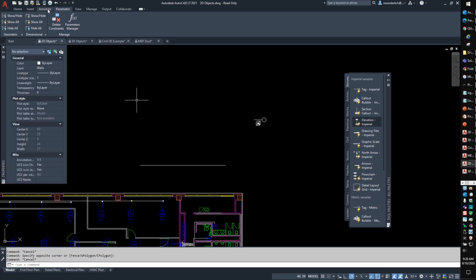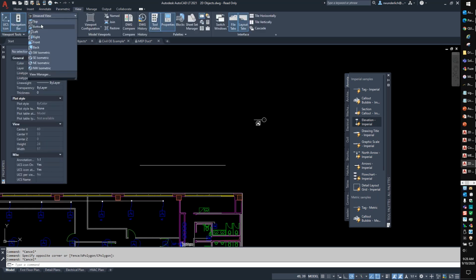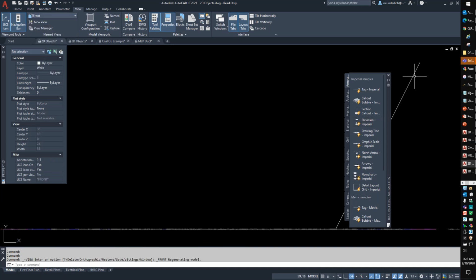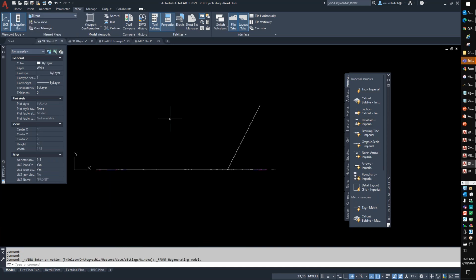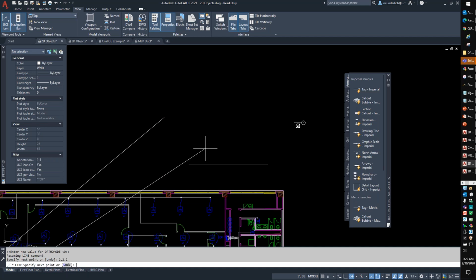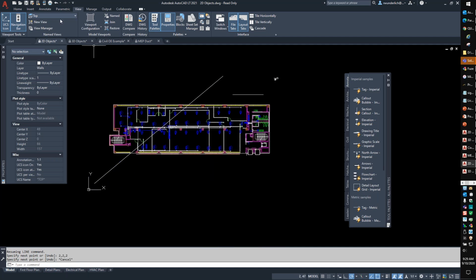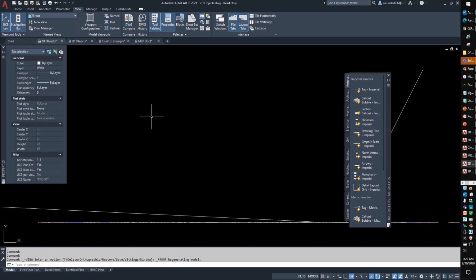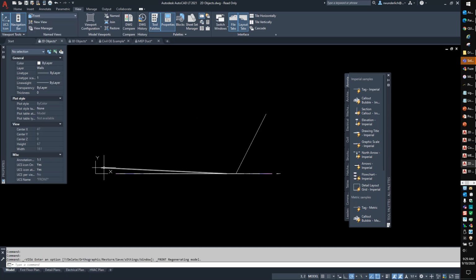Now, if I look at this from our front view, you're going to see that that is now 20 units high. The only other way of doing that would be to type out the exact set of commands. What I mean by that is we start a line here and we want to go at 20 in the direction of 0. Or you can go to 2,2,2. If you're working in a grid situation and I go to front, you're going to see that that line is at 2,2,2. So very limited 3D, it can be done.